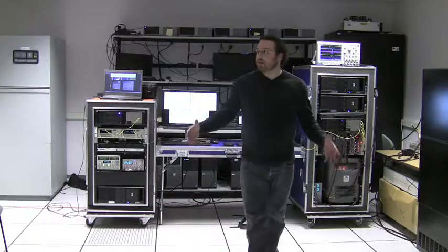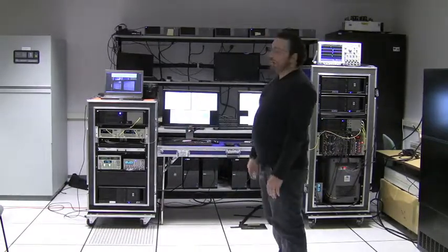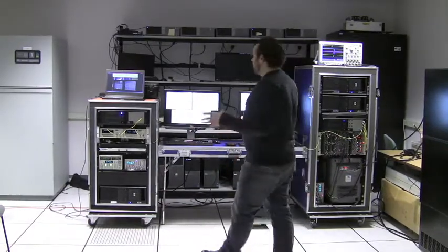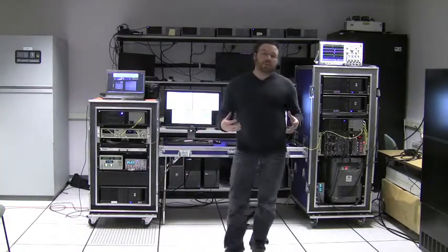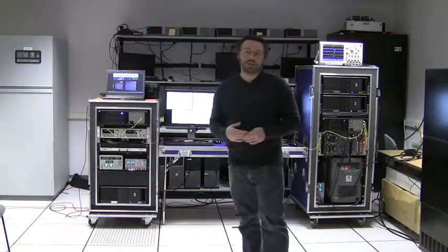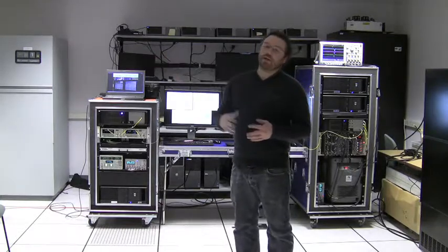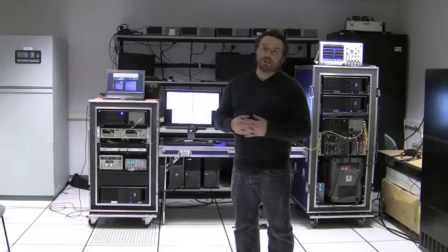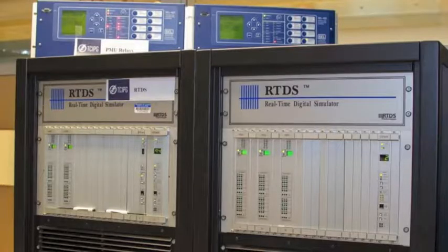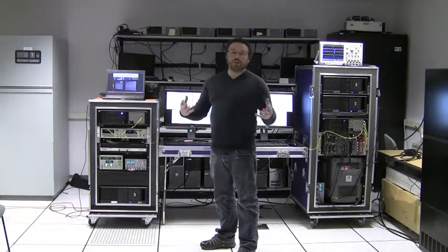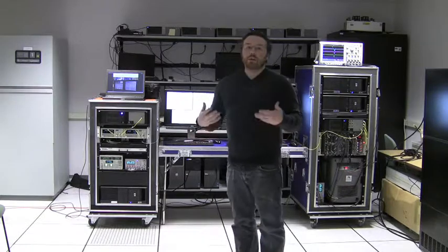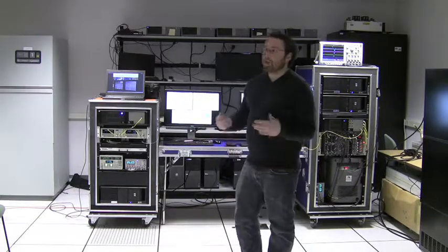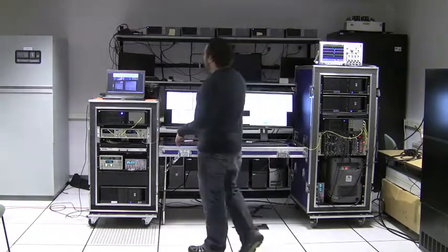So as Beth said, we have a power simulation that's running, feeding data into this. And what we've done is we've set up a high fidelity power simulation running what's called the WSCC 9-bus model. That's running on the RTDS that's here in the TCIPG lab. That's running at a 50 microsecond level power simulation, giving us the real fidelity of deploying this QKD system in the field, being able to verify that in the lab here without actually having to deploy it in the field.